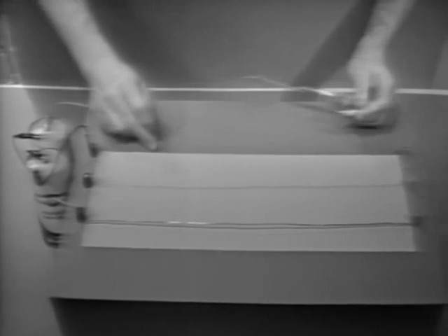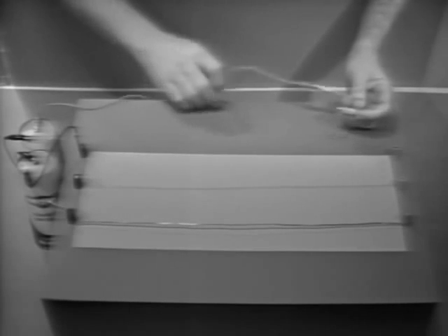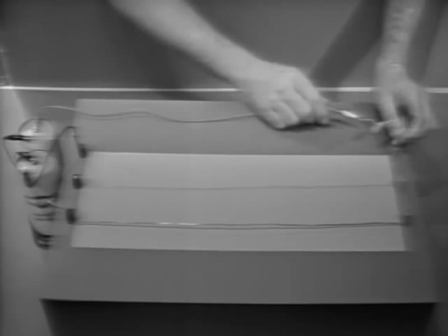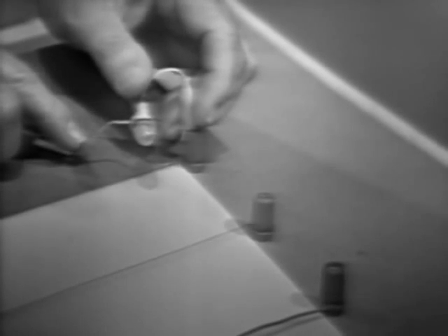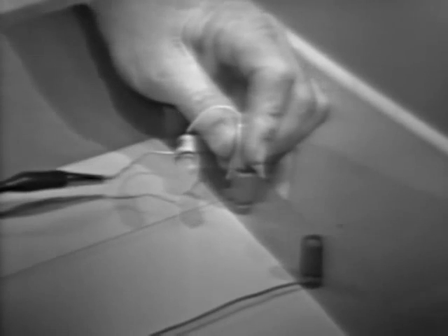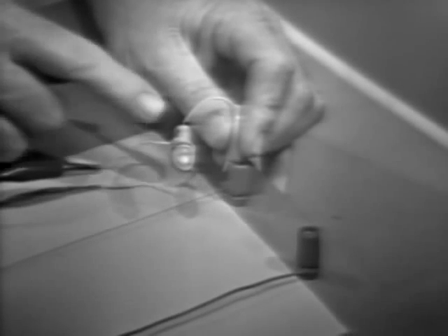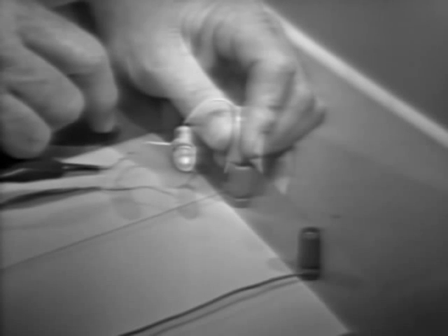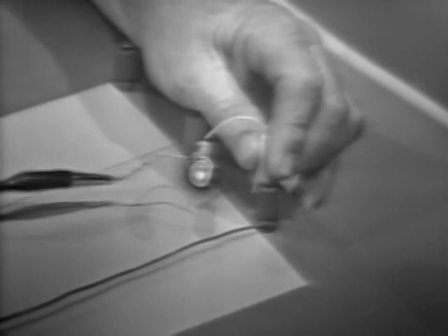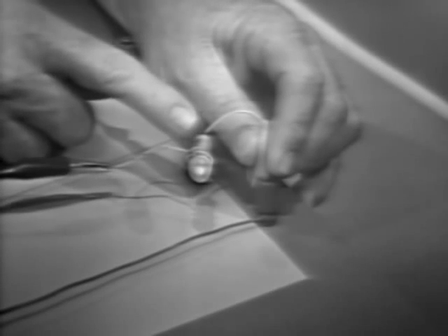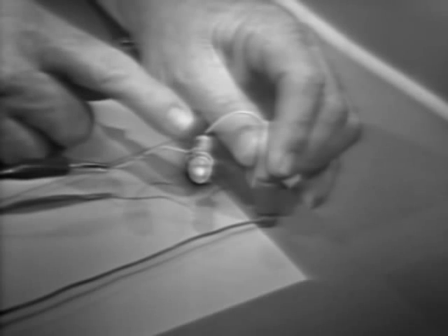Now in the next one, we're going to increase the diameter of the wire. Let's see what happens to resistance as we do this. Of course, with a small diameter wire, there's very little current through the bulb. Let's go to the next one. As I increase diameter, there's more current through the bulb. This means that resistance decreased. Let's go to the next one. Increased diameter, more current through the bulb. So resistance must have decreased.